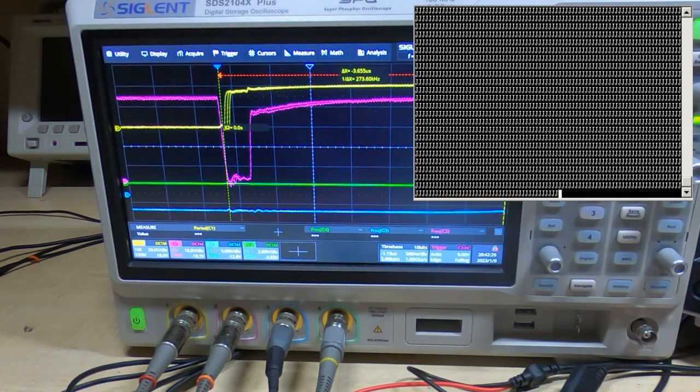and it will work fine. I started with the clock signals when I designed this circuit, and the reason for doing that is to make sure that the timing that we got was going to be correct. But if we take this circuit out and try and use it standalone with a single clock, then of course we would run into difficulties. So that's really what I'm getting at when I'm talking about system design.